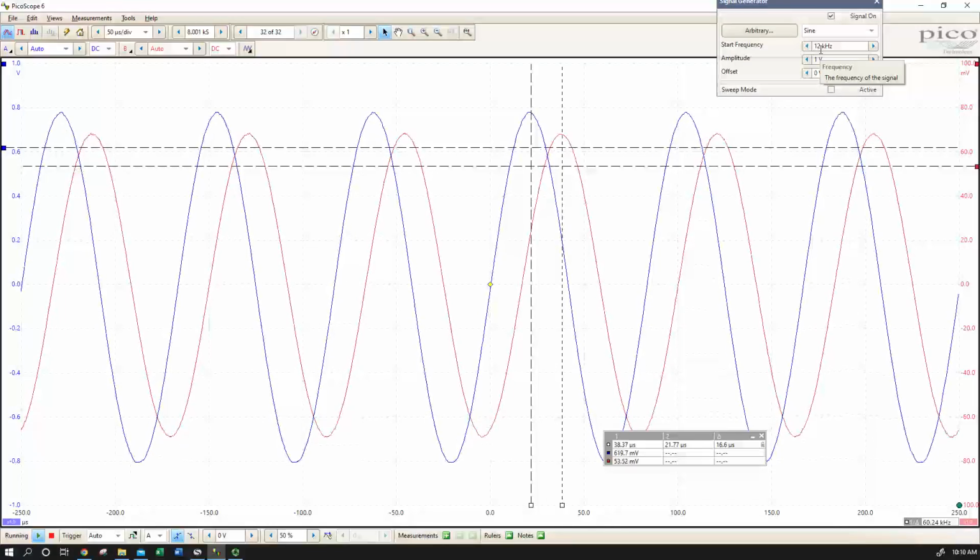When we come back and take a look at the spectrum analyzer, we're going to look at frequency on the x-axis, and we're going to get an instant snapshot across multiple frequencies at the same time of how these voltage signals are responding. So we'll go from a time base to a frequency base, which is where you get these very exciting resonance plots, and how we can look at things like high and low pass filters.